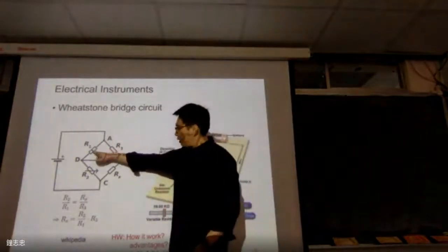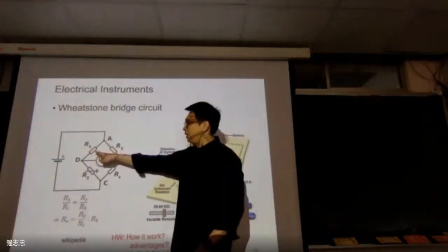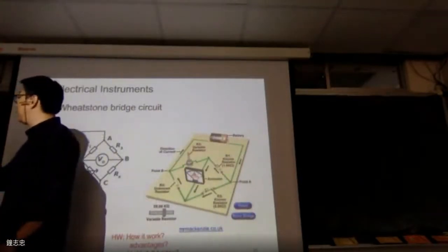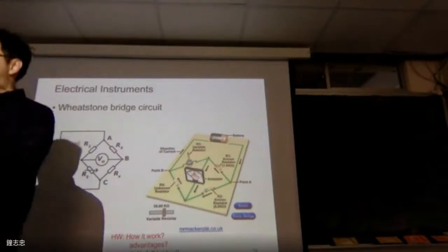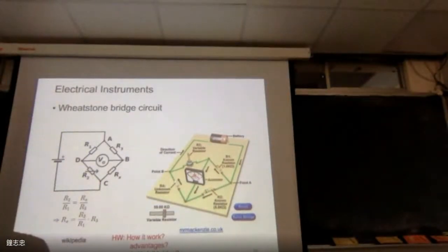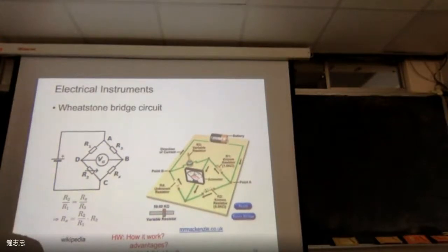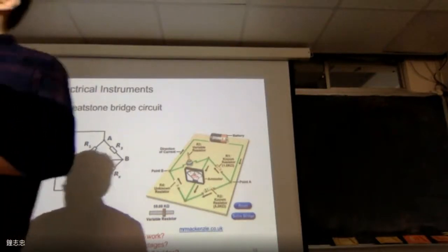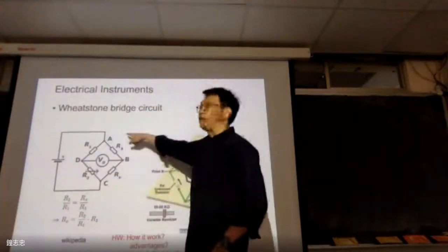For this R1, sorry, we only have this one because the new one is already attached. So you guys can see this is the example from our lab. The blue one is a small strain gauge. I attach this kind of tube for different applications or displacement. So you can find out yourself. So I attach several strain gauges based on the Wheatstone bridge idea.